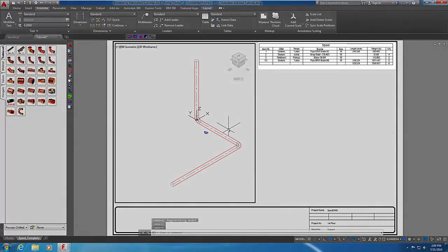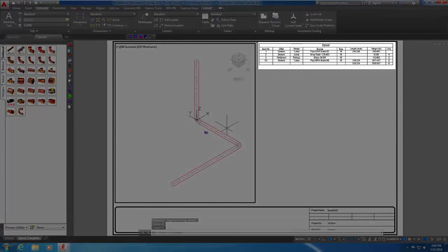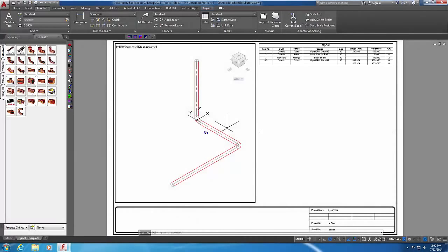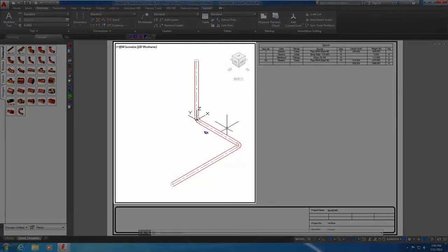The bill of materials on the right side of the drawing is automatically created using the Spool Equipment Report format. The title block is also automatically populated with the job information using the Title Block Report form. The left viewport contains the items that were selected from the model with item numbers automatically placed.